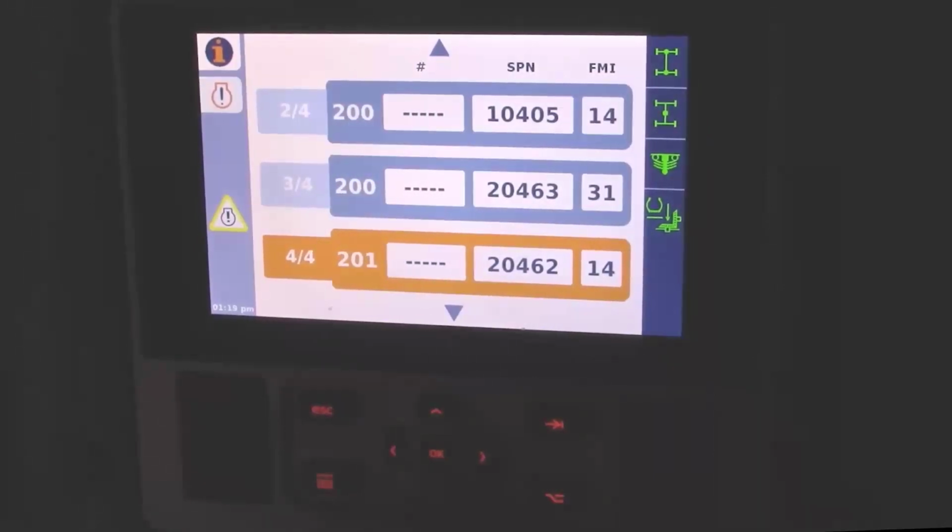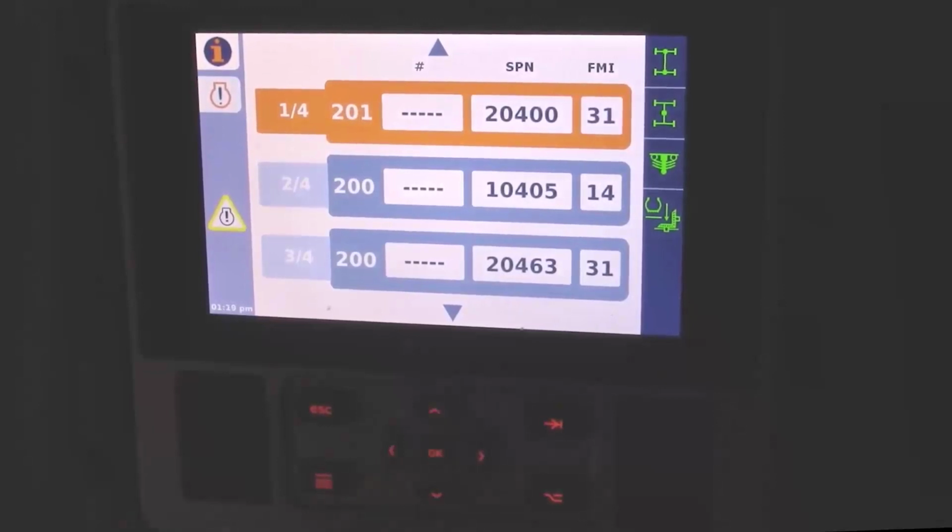And the final option we have is to go to the steering control modules on the rear of the crane. This is a GMK 4100L-1, so it has two modules. Left side is the main module, right side is the backup module. We can then see any errors that may be located on these modules.